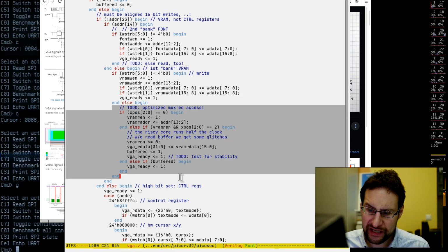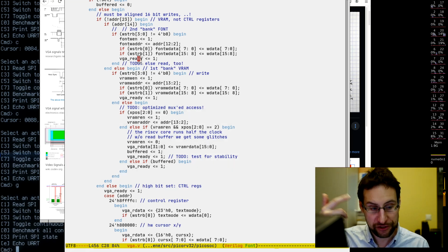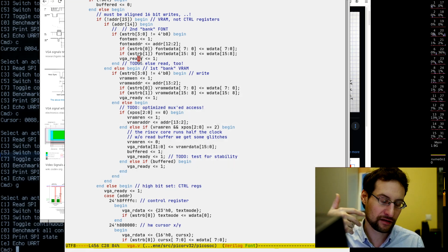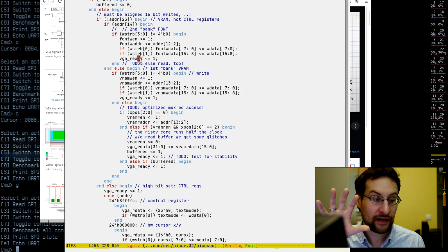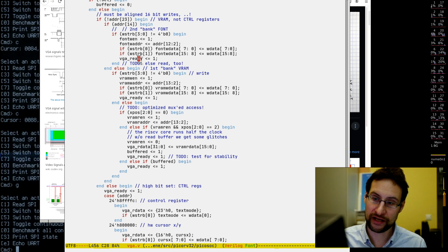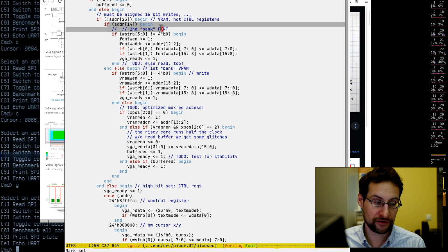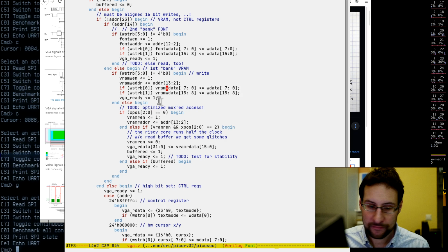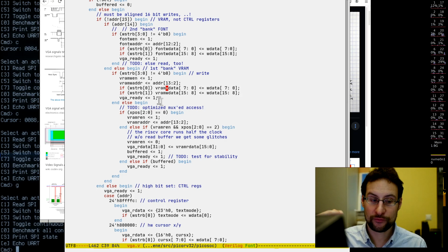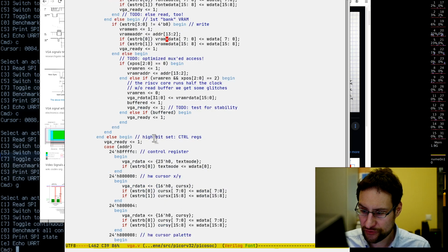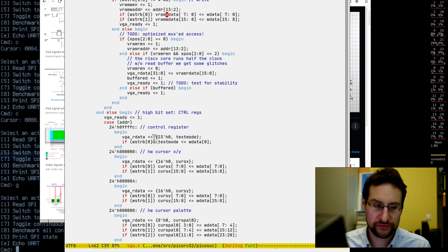Again, reading from the text memory would only copy this here to the text memory. I tried this already. Right now I have only a couple of 10-20 logic elements left. Previously I had already 101% used. I had to already optimize the heck out of this address bit decoding stuff. So most likely I will at this point in time not waste any logic cells for font reading, because, whatever. Just don't do this, just output data to the frame buffer.